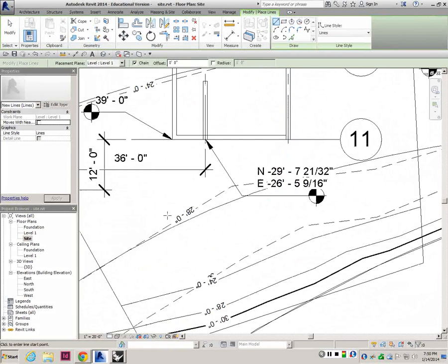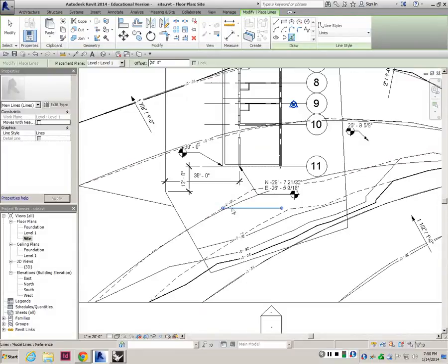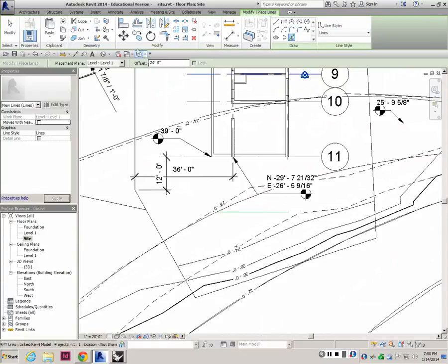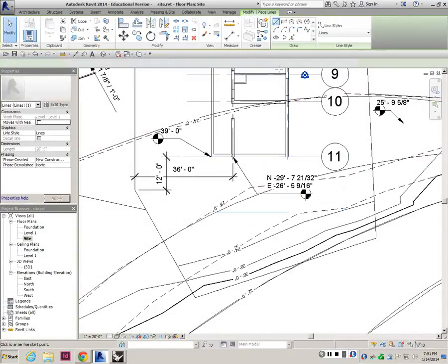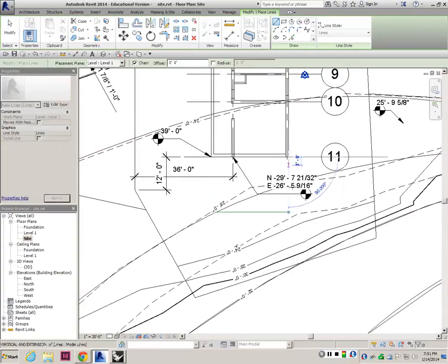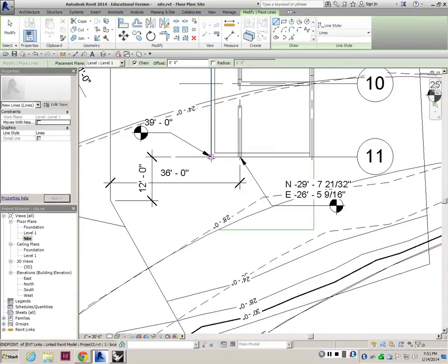So first let's create some sort of an area here, like a little square, and that one I'm going to do using pick lines. So I'm under model lines and I do pick lines, and offset I'm going to use 20. And I come here and create one model line there, and we could create more. Let's add some more here. Oh, I'm in pick lines still, so let's go back again, create similar. Offset value is 0 now, so I put one here, put one there.